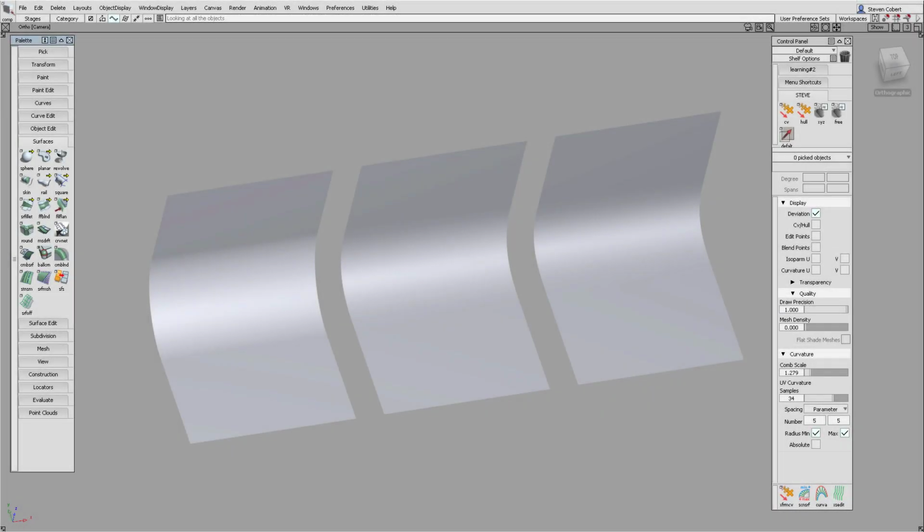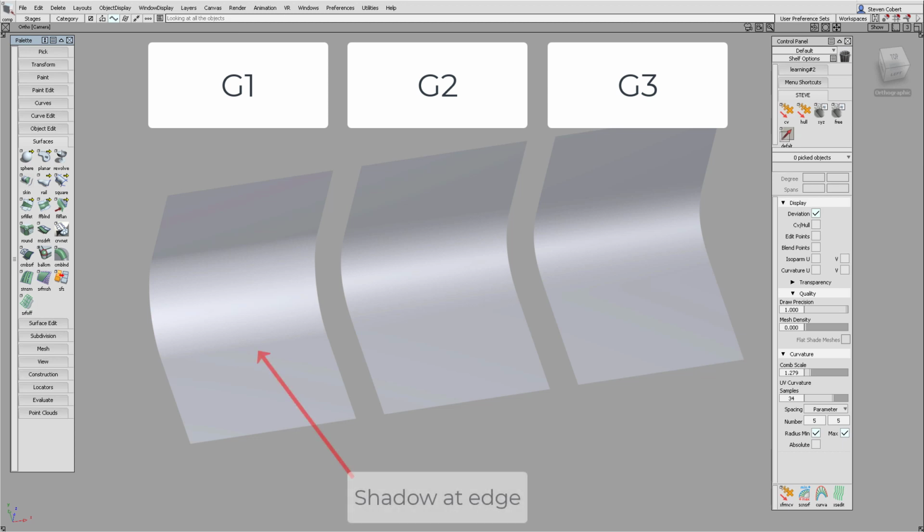We've already said that G1 fillets are generally avoided because they give a very hard looking edge, as you can see here. In fact, they make the block surfaces look hollow. If you look at most mass-produced industrial products, you'll see these types of fillets. I've even seen them in train carriages. In the car industry, though, they're generally not acceptable. The only time that G1 fillets may be allowed is if they're very small, say less than 5 mm, or if there's limited space.